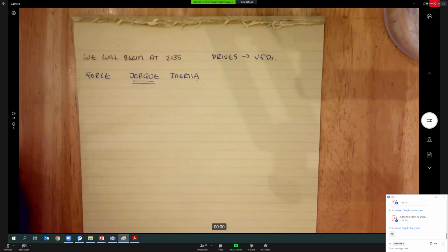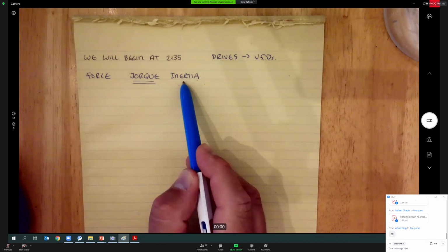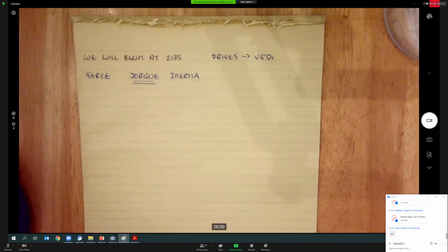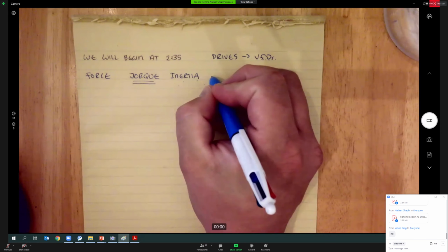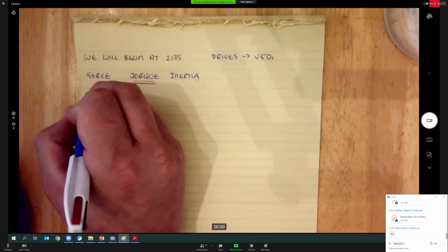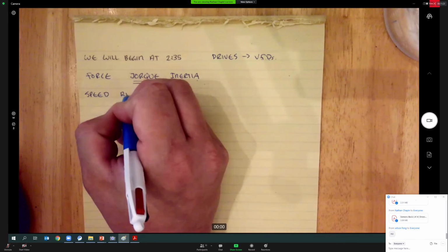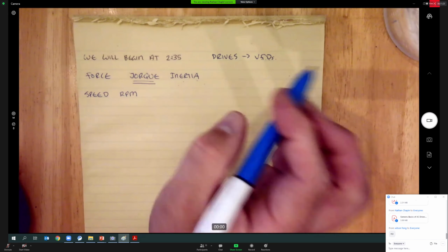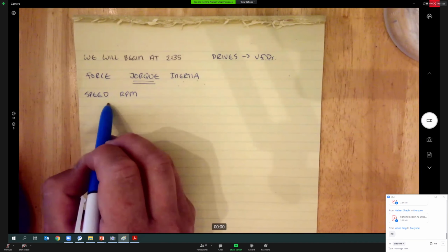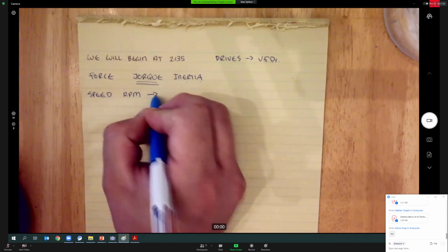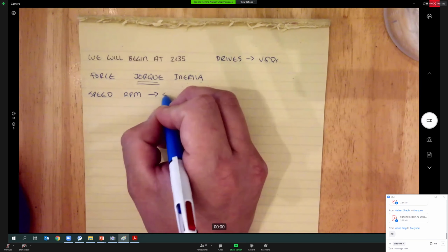If it's not, it can fry the motor, it can fry the VFD, it can cause nuisance tripping in your electrical system. So there's all sorts of things. So the inertia of the load is very, very important. Now, speed, we'll go down here. Speed, obviously, we're going to be talking about revolutions per minute. And with speed, let's just talk about a motor starter.